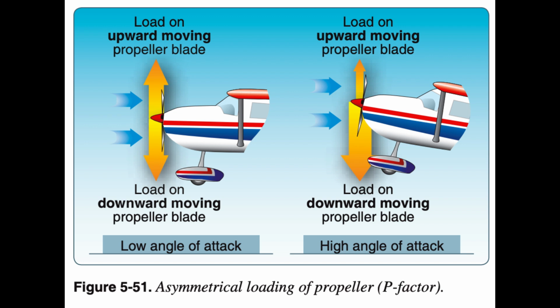Thus, the blade proceeding into the horizontal airflow is creating more lift, or thrust, moving the center of thrust toward that blade. Visualize rotating the vertically mounted propeller shaft to shallower angles relative to the moving air, as on an aircraft. This unbalanced thrust then becomes proportionally smaller and continues getting smaller until it reaches the value of 0 when the propeller shaft is exactly horizontal in relation to the moving air.